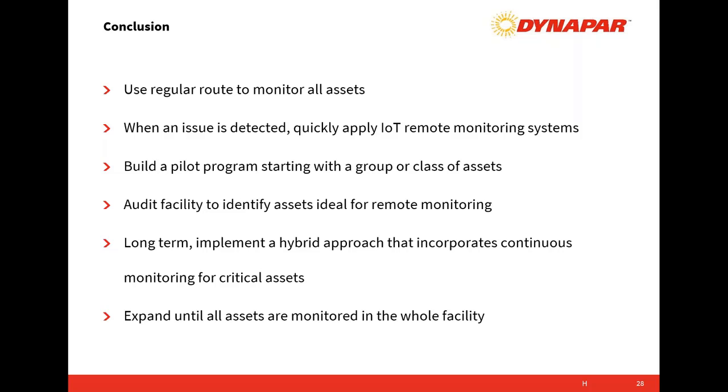The anomalies that we're looking to detect for motors could be anything from unbalance to structural looseness to misalignment to electrical problems, bearing defects. So there's a wide range that remote monitoring can do. You can imagine a route-based analyst coming in once a month to take data, and they may miss something in between. Having remote monitoring for motors, we can catch almost everything the analyst is catching, as long as we're taking periodic data. So you're able to catch everything route-based is able to catch.